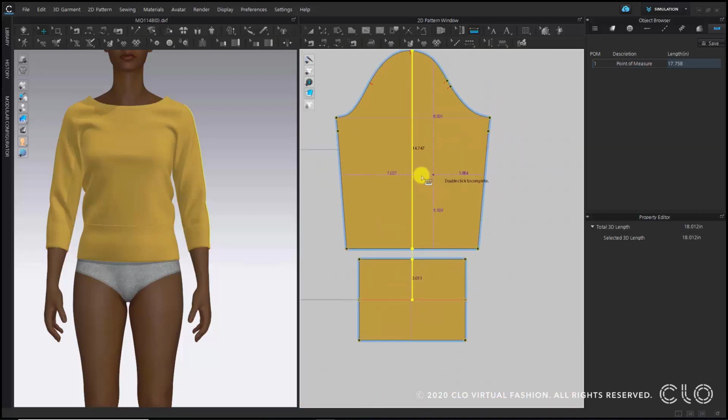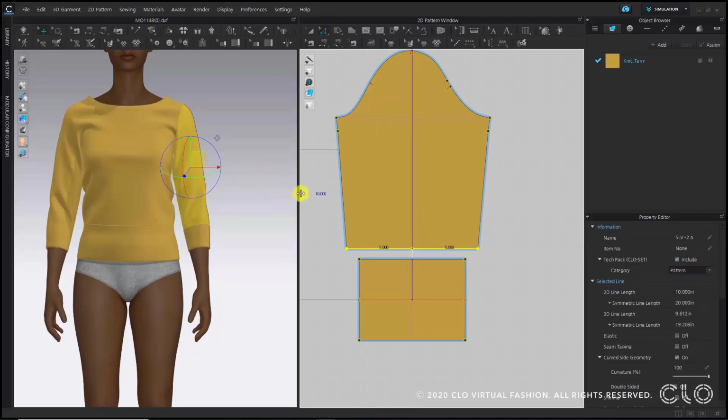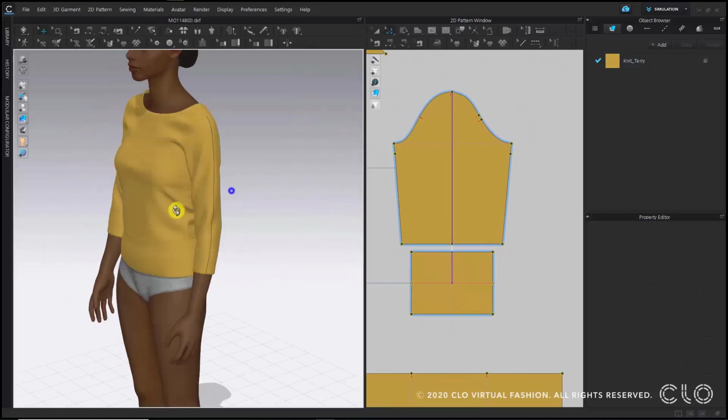And then I can see here the measurements on each pattern piece before I start reducing it by the amount that was requested. In order to do so, I will first reverse my high resolution properties. So before editing my pattern piece itself, I also have to remember I need to change my resolution settings.